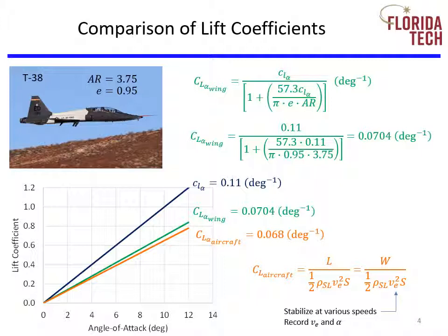Second, you could use the lift curve of actual aircraft test data. The lift curve must be available either from wind tunnel or flight tests, and the angle of attack must be known. Not all aircraft have instruments to measure angle of attack. And third, you could use the special relationship between induced drag and parasite drag for a known optimum performance condition. For example, if you're flying at L/D max, it can be shown that induced drag is equal to parasite drag. The aircraft drag polar, however, must be known.